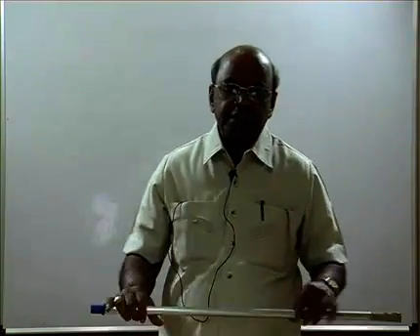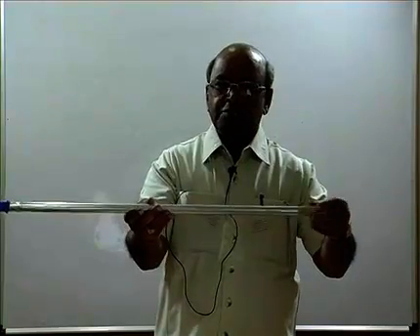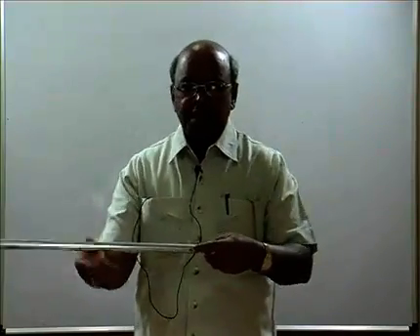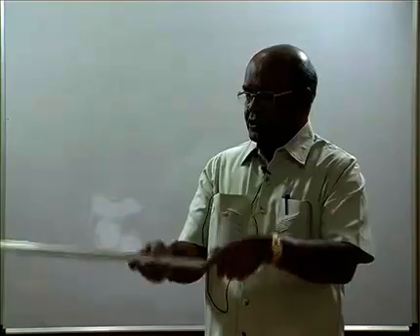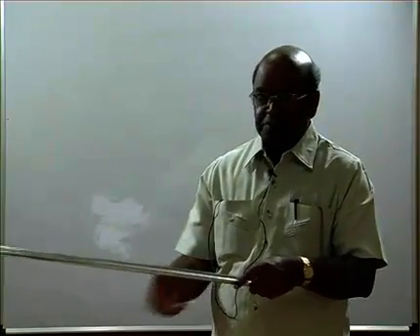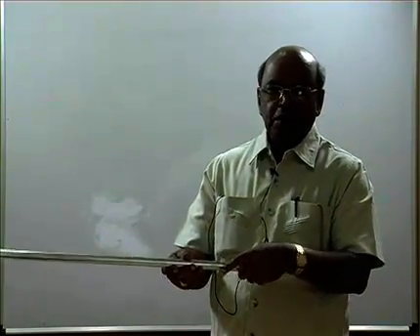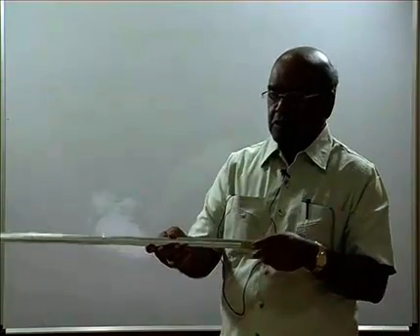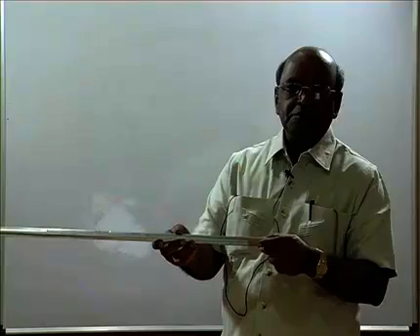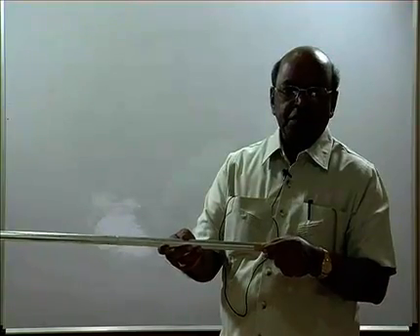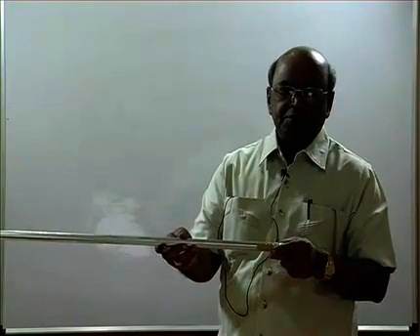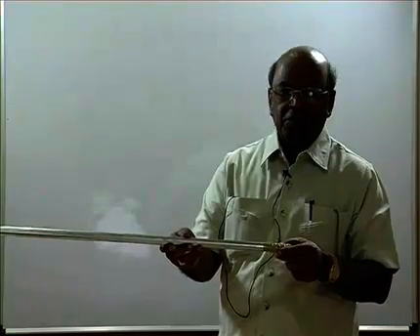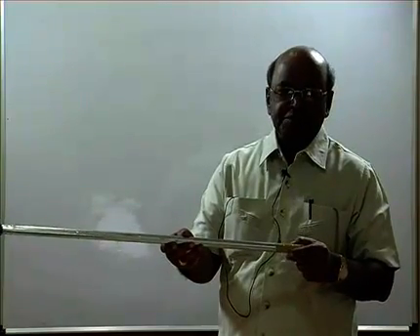So what is number 1? Number 1, you can see the straight line parallel to both HP as well as VP. So take the ground or table surface as the horizontal plane and this one as the vertical plane. Now the straight line is parallel to both. So this is the simplest of all the positions, so we call this the simple position.